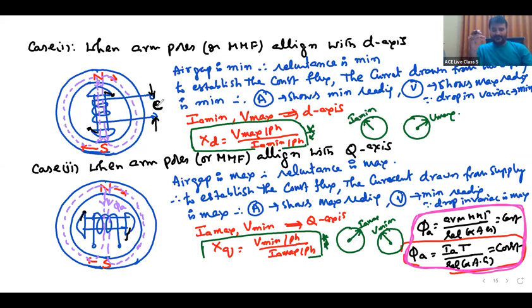We are not giving DC excitation in this experiment. So the induced EMF in the field winding is AC, and the shape of the waveform is sinusoidal, at slip frequency. That's the question. During the slip test, the induced EMF in the open field winding is: A, AC; B, DC; or AC sinusoidal, AC rectangular, AC at slip frequency, AC at supply frequency, like that. Only one statement is correct: the induced EMF in the open field winding is AC sinusoidal at slip frequency.